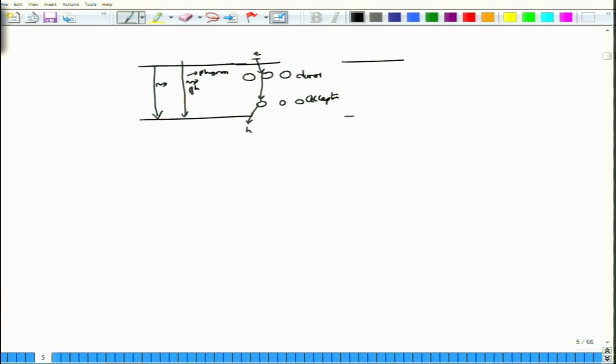Finally, or as a last example, you have an interesting transition. So, when there is an electron to hole recombination, it will emit a photon, but then this photon energy will be absorbed by an electron here, which will then move up into the state. So, it will actually take up the electrons in the conduction band, will take up this emitted photon energy and then move up in the energy level. So, this process is called Auger recombination, and the problem with this Auger recombination is that it is proportional to the cube of the carrier density.